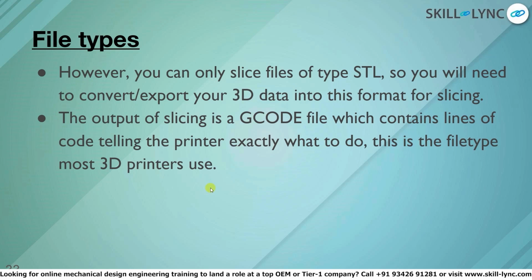What you need to know right now is that you create your 3D model, obviously using a design for 3D printing in mind. You export your 3D CAD model as an STL file. You slice that STL model and you generate G-code, and that G-code can be sent to a 3D printer, which will read it and automatically print your model. That's all that there is in concept.